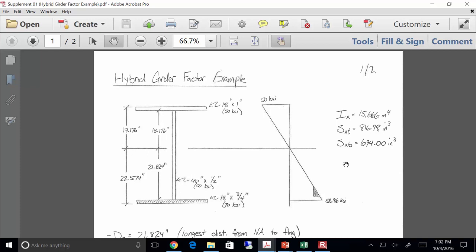Looking at these grades of steel, I guess right off the bat that I'm going to reach 50 KSI up here before I reach 70 KSI down here. Reasonable guess? Let's see if it's accurate. I have an I-beam with these dimensions. We should by now be able to compute the moment of inertia of that, and also the section modulus of the top and bottom. I've got the centroid and everything listed here. Everybody all right?